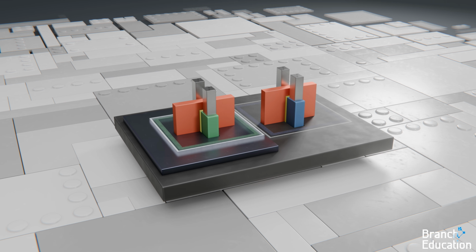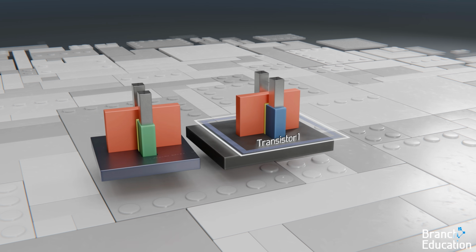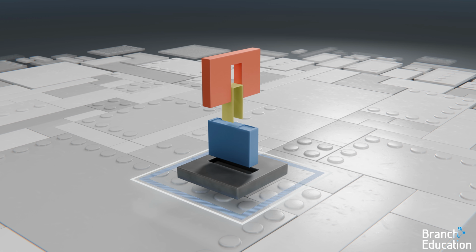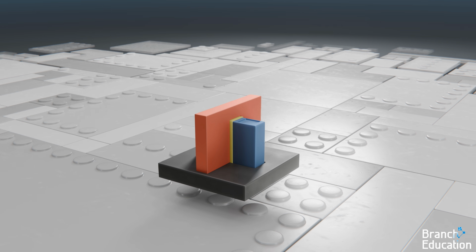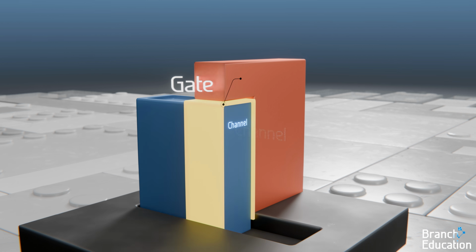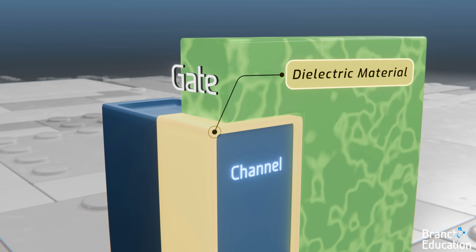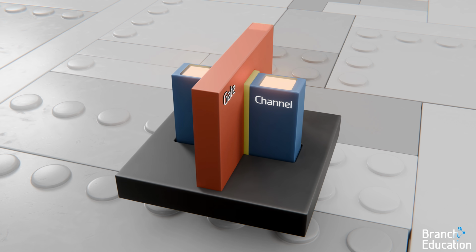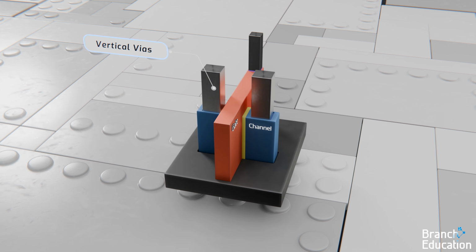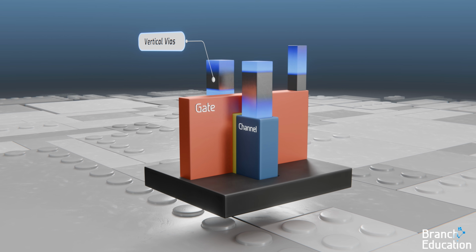At the bottom of the standard cell are 2 transistors built on top of a silicon base. We'll focus on one of these transistors, which has been simplified a little bit for the sake of this explanation. Inside this transistor are a few key parts: the gate, the channel, and the dielectric, which is a barrier that separates the two and prevents electricity from passing through. Additionally, on either side of the channel and above the gate are metal contacts connected to vertical vias that are used to input and output electricity to the corresponding parts.